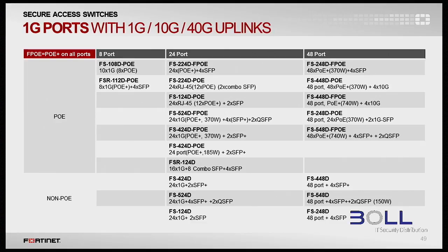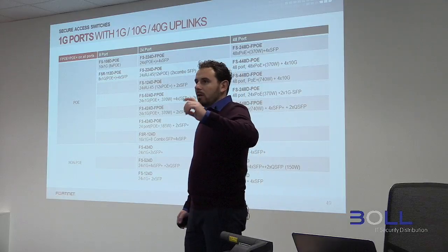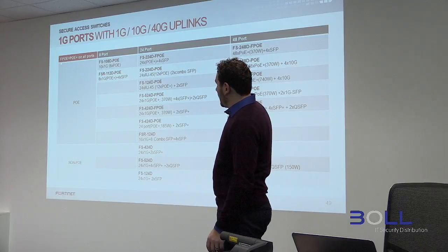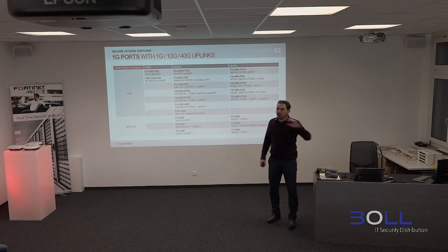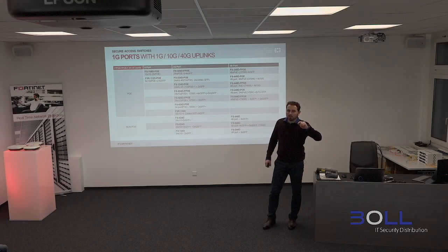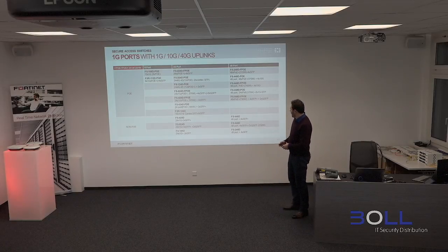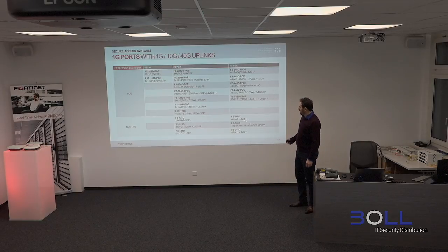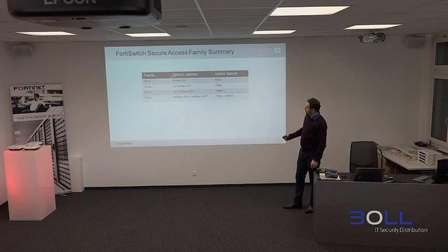And then if you look here, you see many different options of PoE, but what's important is that FPoE means that all the ports are PoE, and they are all AT, so the PoE plus support that can offer 30 watts of power. And you have also non-PoE models. So depending on the uplinks, you can choose the models.